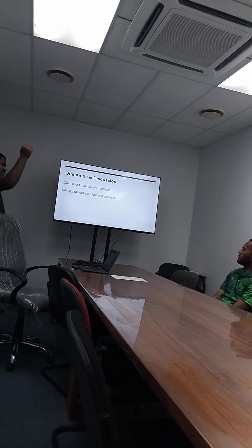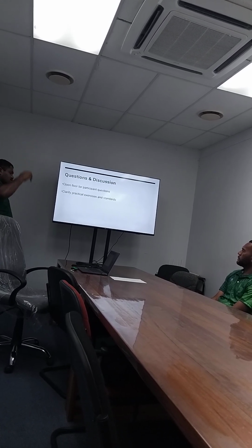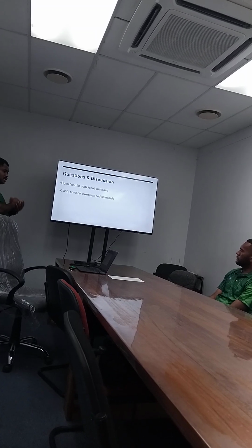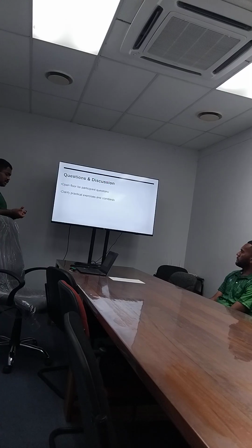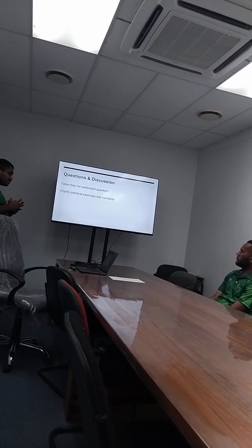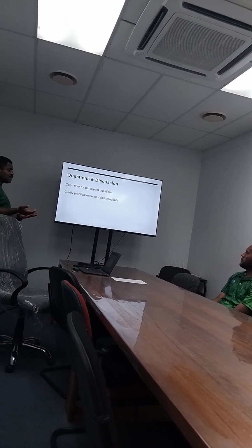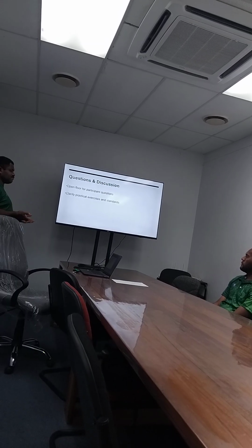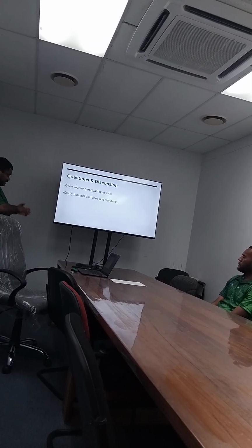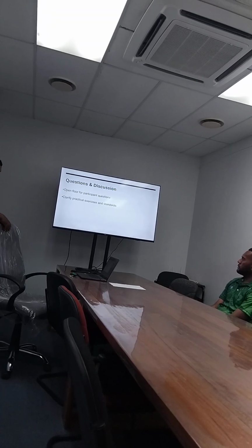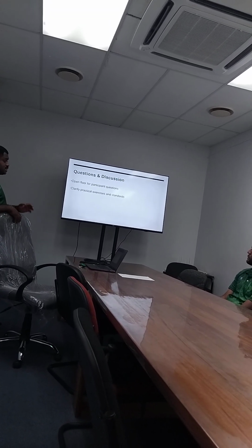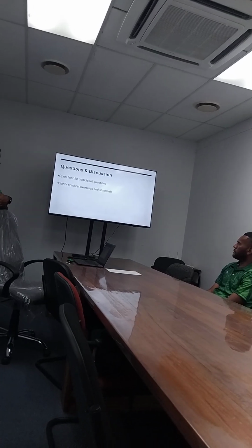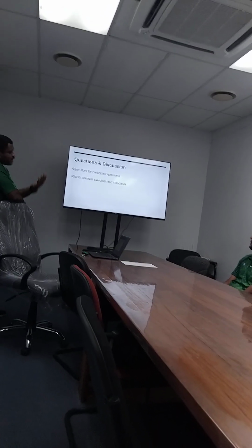Like I said, ADSB data is received on the receiver, onto the RPU, and timestamped. If there's no valid position coming from the GPS antenna, there's no correct time. What happens? It cannot timestamp. Therefore, every data received is invalid. It won't send anything, it will be gray. That's to do with GPS or GNSS on the ground station. The same will apply to the aircraft as well.